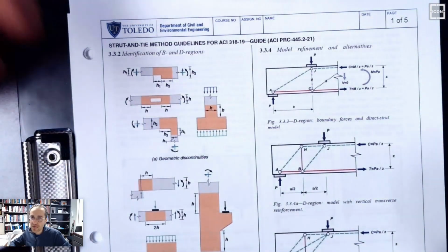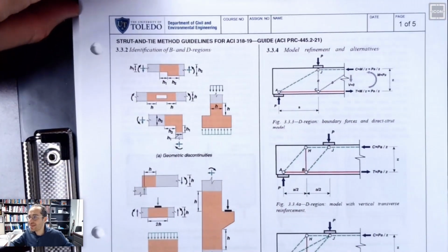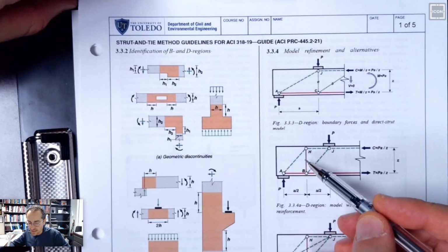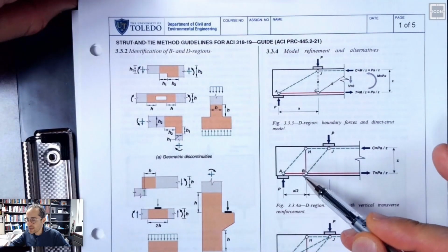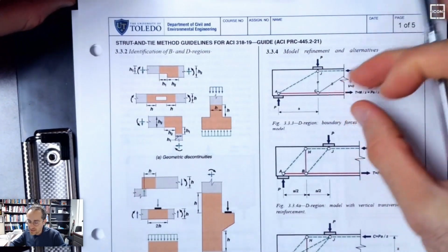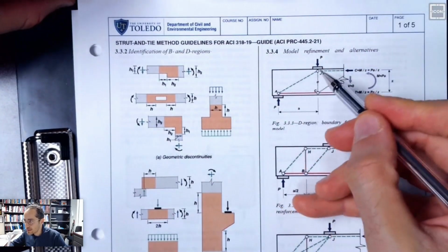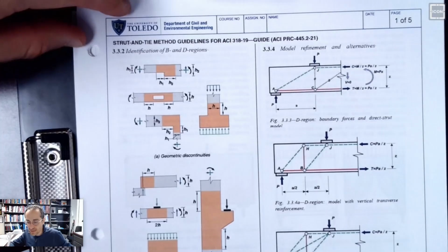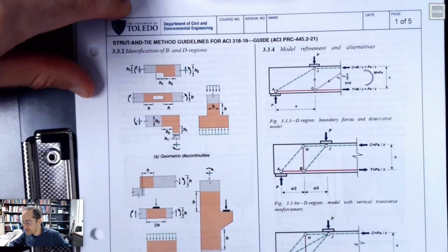If it's a new design, you can make it deeper. You can make it deeper to avoid this inefficient mechanism in terms of lifting the same force. So increase the thickness, increase the depth of the section, make sure that your angle is good and you can directly go without any ties or any straps. So that is the approach.